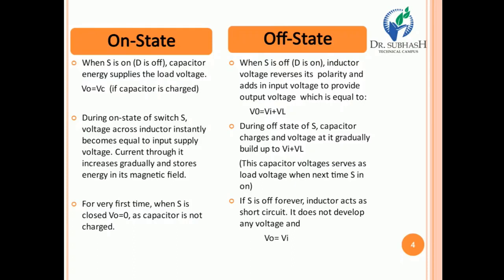Now in the on state, during the on state of switch S, the voltage across the inductor becomes equal to the input supply voltage. Current through it increases gradually and stores energy in the magnetic field. The very first time S is closed, the output voltage is equal to 0 and the capacitor is not charged.